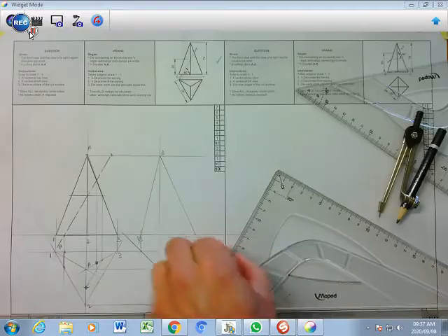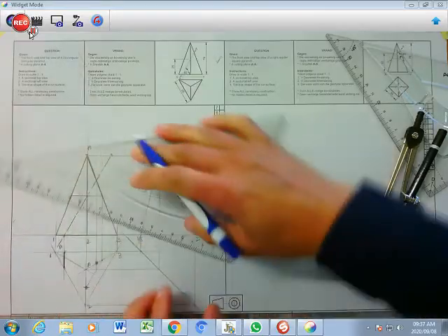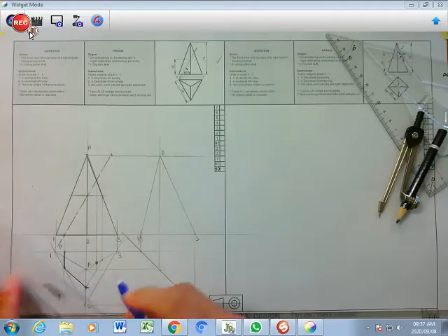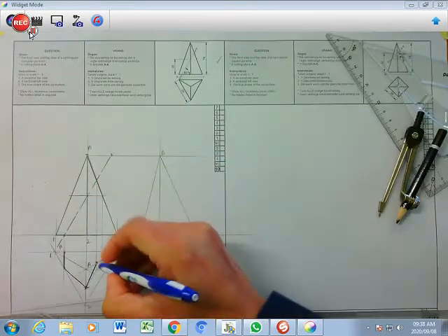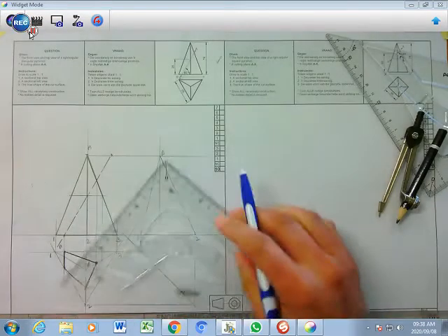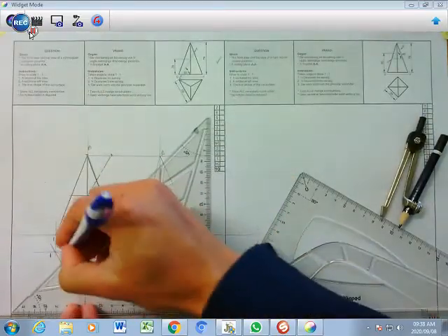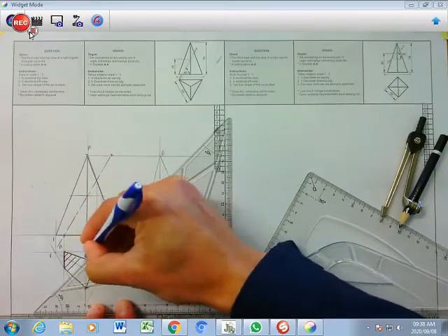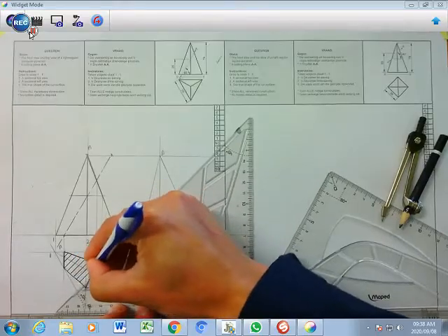And then once I have that, I can now darken. I want to start darkening that there. This line is going to go from here directly till there. Then this is going to go to that point over there, and then it's going to go to that point over there. Right. And then you can do your hatching. The hatching can be at 45 degrees. So that's going to be hatched like that there. That is just to show where the part has been cut.